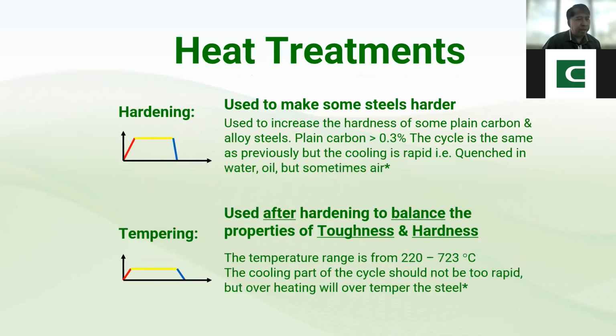Ano naman yung quenching or yung ibang tawag dito hardening? Same heating rate, 200. Same soaking temperature. Kaya lang ito, basain mo ng tubig, basain mo ng oil. Pag oil quenching ang tawag doon. Pag water quenching. Ano nangyayari sa ating bakal? Tumataas ang hardness ng ating bakal.